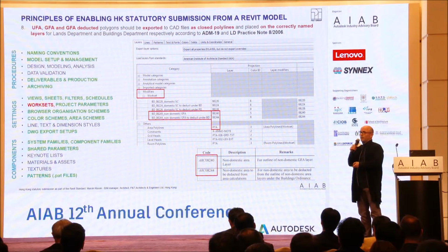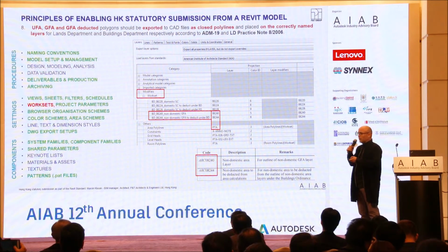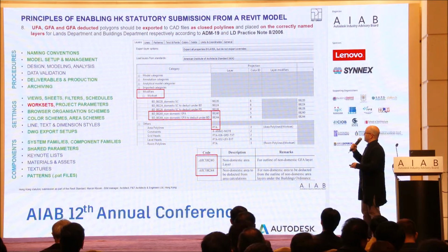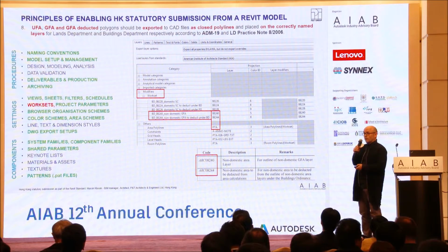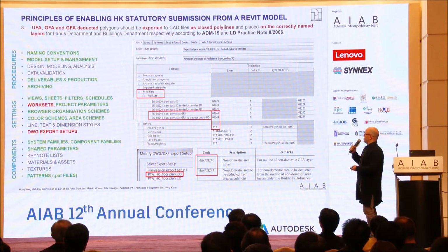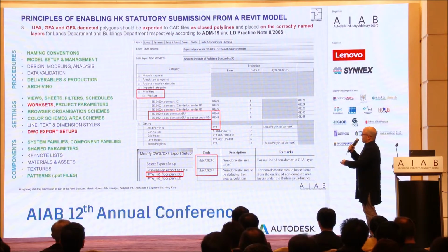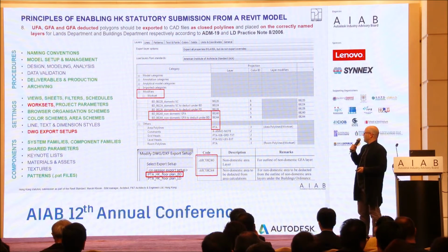This is all done without any plugins. Plugins help, but a lot of this can be done just by setting Revit properly and having a proper standard. So, all this results in a DWG Export Setup, which is named, for example, floor plan BD. That's for building department. The other one would be LD for lands department.